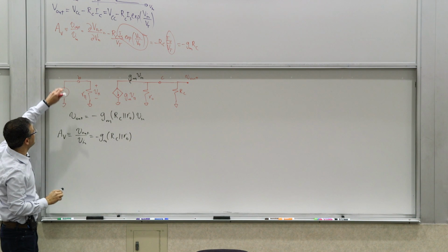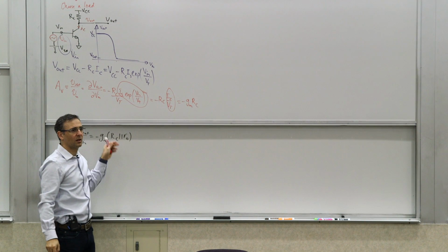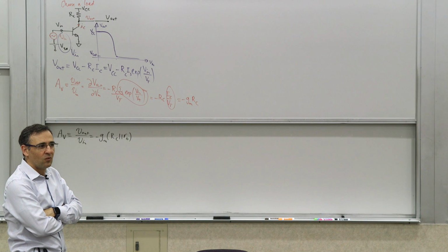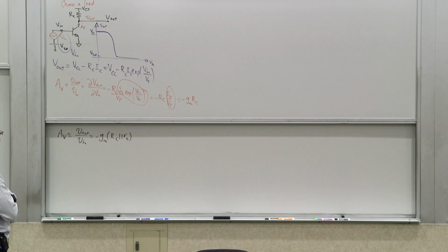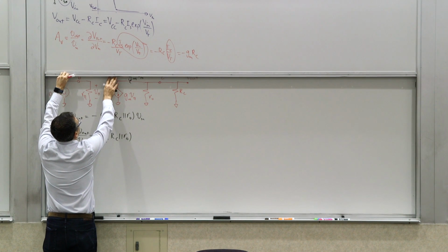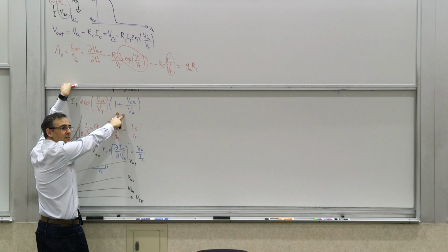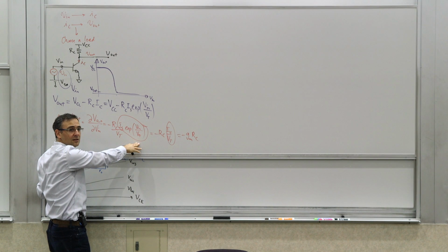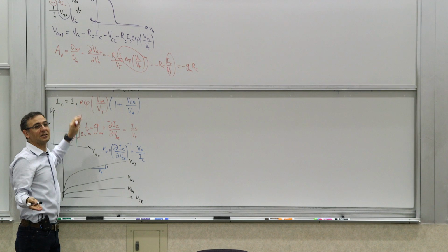So is this the same result as this? Well, not exactly, right? It doesn't look exactly the same. There's the second term, RO, which wasn't in there. Why wasn't it in there to begin with? What did we approximate out that led to this? Well, we remember our friend here, right? The Early effect, this blue one. We did not include that, and therefore we didn't see its effect. Had we included that, we would have seen its effect.